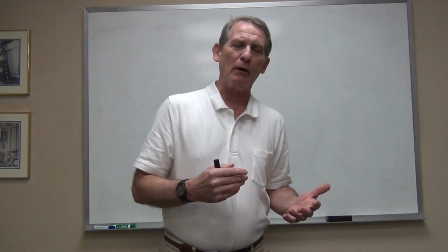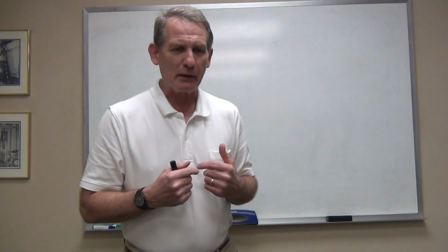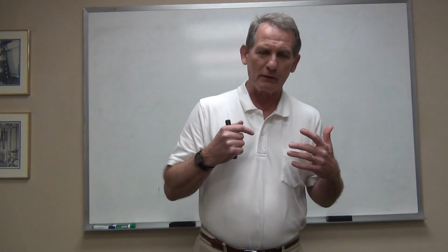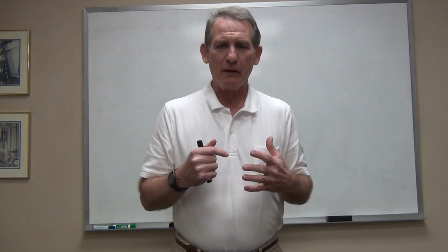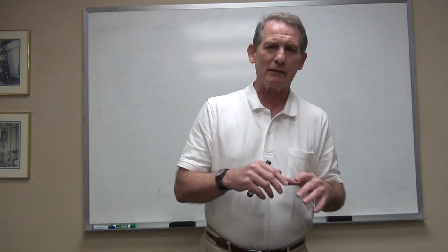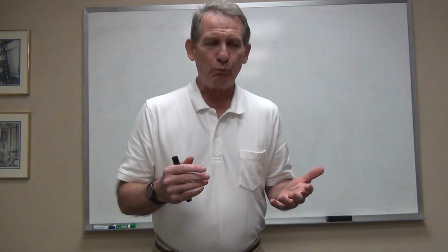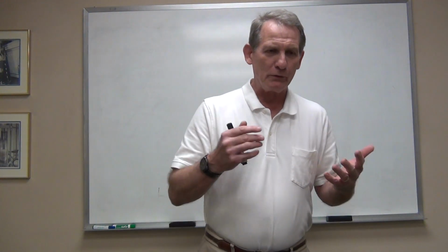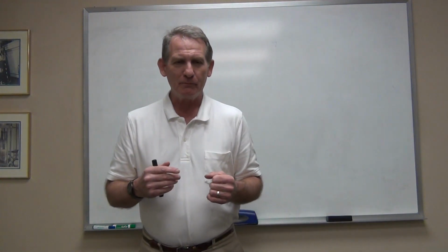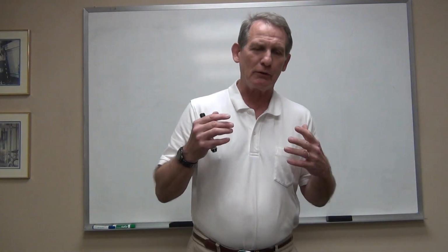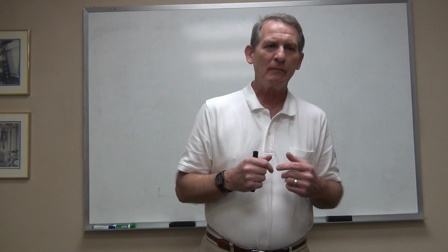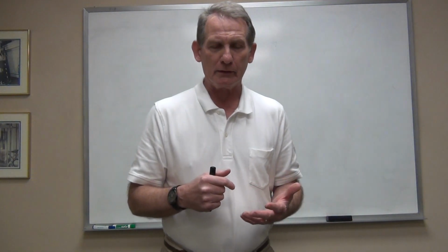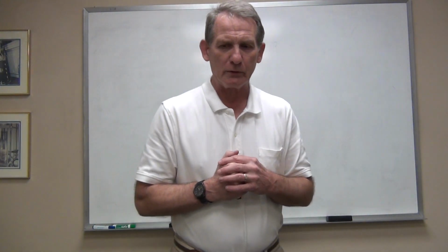You can say, well, I've got a straightness tolerance here that's fairly tight, but for some reason when I heat treat these things, they bend a little bit. What would you do? You would take advantage of that. You would turn the shafts down closer to least material condition, and that would give you that additional straightness tolerance. So that's that idea of a bonus.